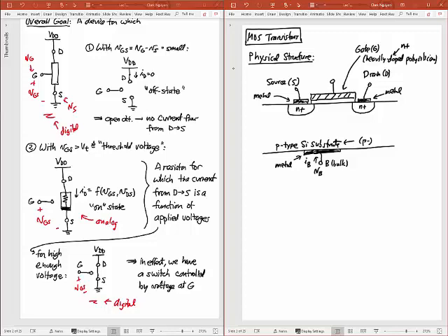This also nowadays is becoming metal. Okay, so we're able to use metals now as gates nowadays, but right now we'll just talk polysilicon because that's what your book does. I can call this voltage VG, and this voltage I can call VS, this voltage I can call VD. Okay, and I'll have a current flowing here, maybe, that I can call I sub G. This current here is the current really that's going to flow generally between the drain and the source. So oftentimes this is going to be called IDS. That current right there.